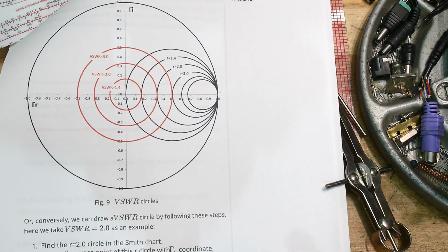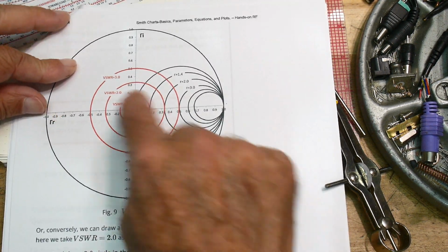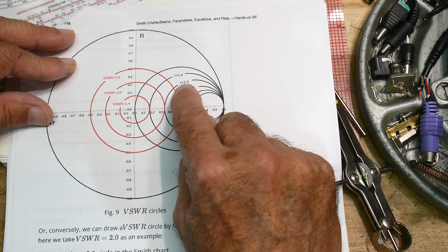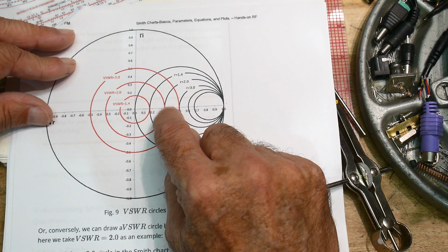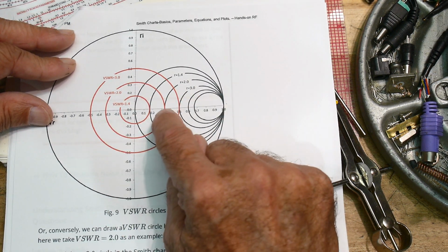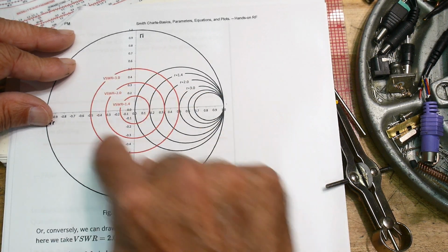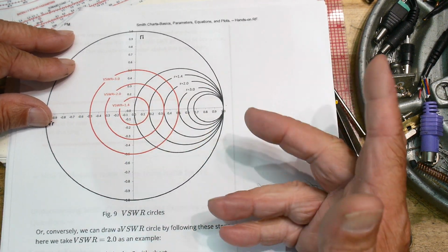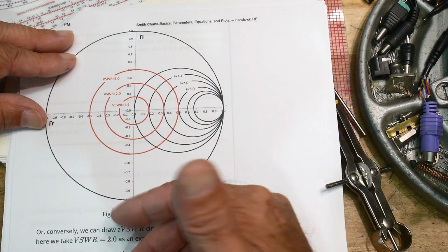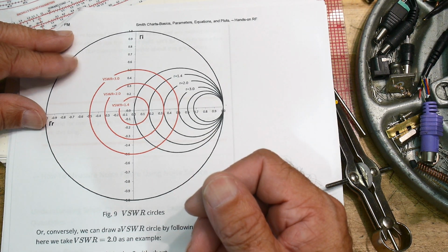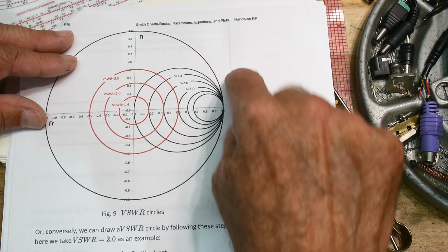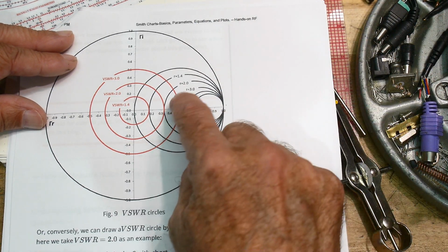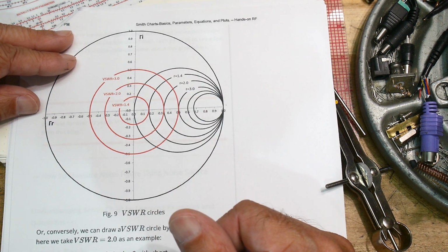And in case you do get around to reading the paper, it actually has these SWRs as well, and it shows you that if you have like an R equals 2, then your SWR is 2. And if you have an R of 3, then your SWR is 3. So it's the intersection of these R curves, and allows you just to do it, because it's just R over R, it's just V over V. Remember, fundamentally it's V over V or Z over Z, and that's just impedance over impedance. So that's all these things are, is ratios.